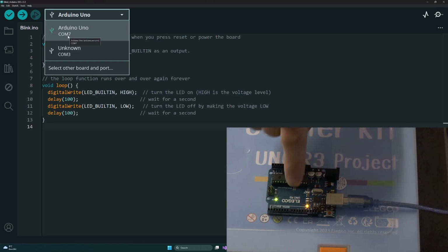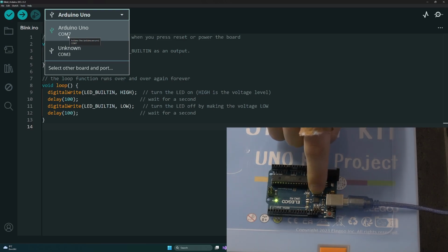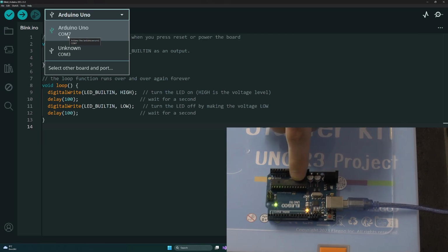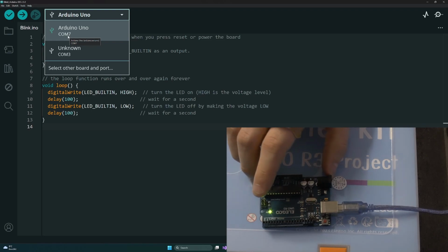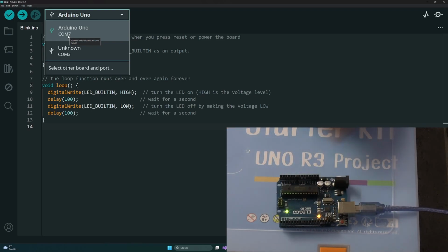Basically, there's this chip on here that's emulating a serial connection, because, well, the Arduino, of course, doesn't speak USB, but this chip does. This chip does speak USB, and the software on this chip is luring the computer into thinking that it has a serial RS-232 connection connected. It's not really always RS-232 because it could be multiple ones, and there's a bit more to it than just RS-232 versus COM ports in general on Windows. But in general, it emulates a very, very old but simple interface. And this simple interface is used by the Arduino IDE to upload data.